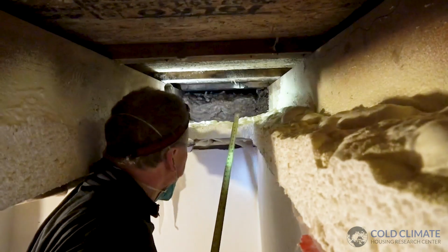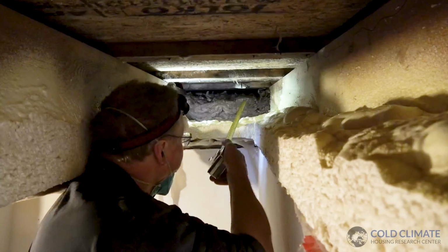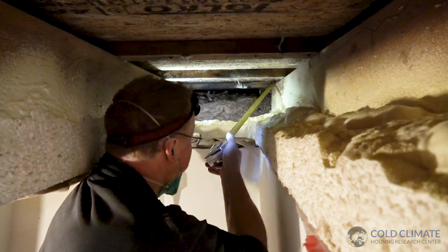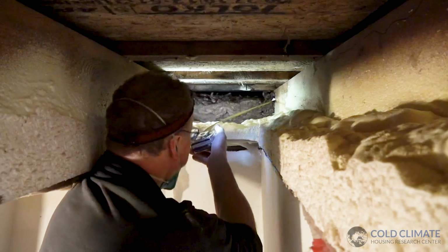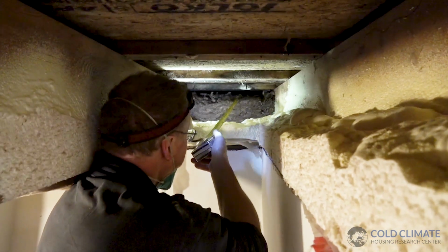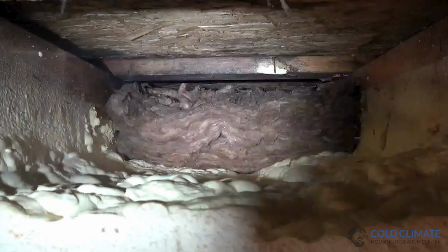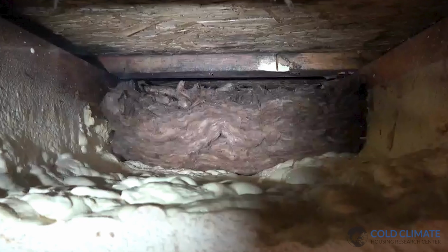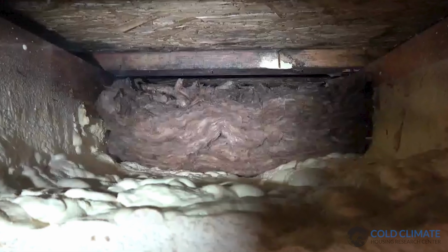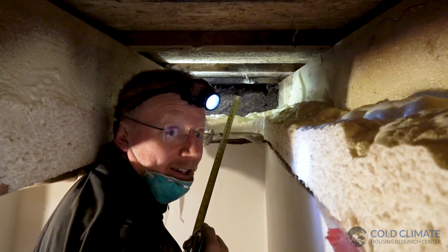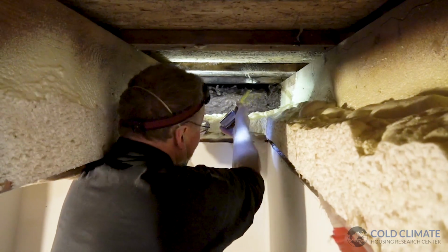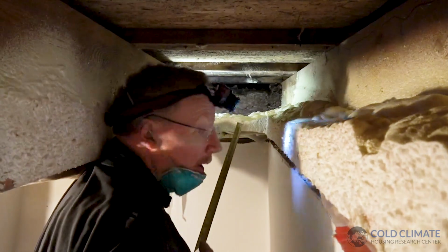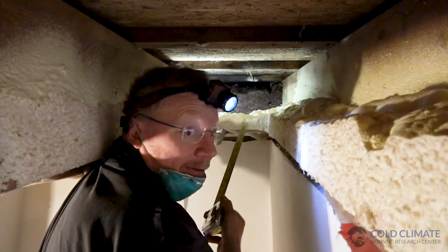We're now looking further up this rafter bay beyond the closet, and this is the rafter bay right next to our common wall. And we've already pulled this insulation down to get a look, but this insulation was completely blocking this vent space. And remember, when I reached over the rafter, that insulation there was still wet from condensation last winter. If this vent space wasn't blocked by insulation and were working properly, you would have a drying path.